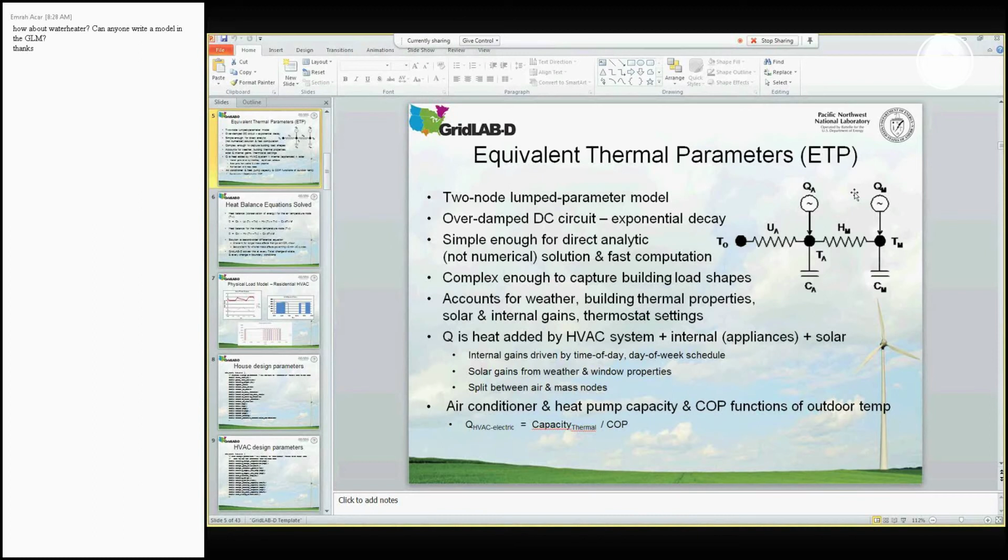So you can almost think about it, looking around here, there's basically a control loop that's built around these two guys. When T-air exceeds a certain threshold, you activate the HVAC system, and it does something to modify TA. But because of these other damping elements, it has different behavior than if you just put that into what's called a single node model and try to push that energy around in that way. So effectively, what we're trying to do is balance simplicity and complexity.